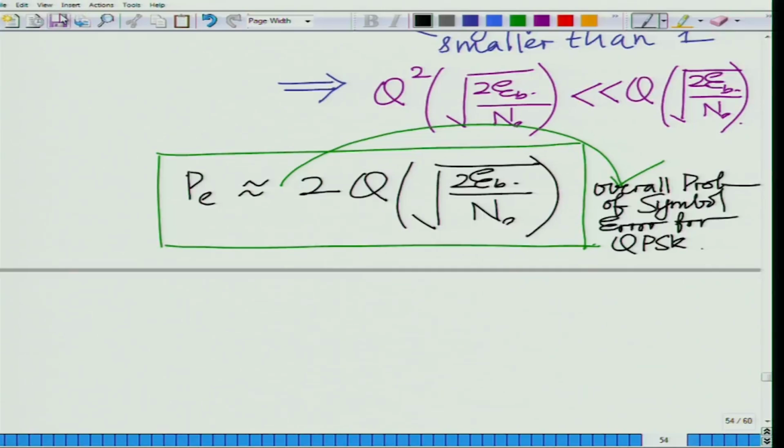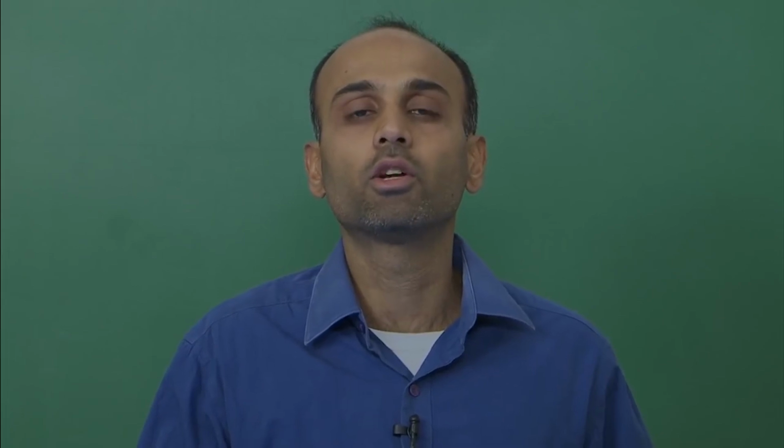So basically what we have seen in this module, and in continuation of the previous modules, is that we have thoroughly examined this new modulation scheme, which is QPSK, and it is very interesting because we have used the concepts of signal space. We are using two orthonormal basis functions, that is a two dimensional signal space with orthonormal basis functions p1(t) and p2(t), and we can transmit one bit along p1(t), by using pulse p1(t), and another independent bit along p2(t), and both these bits can be recovered at the receiver.